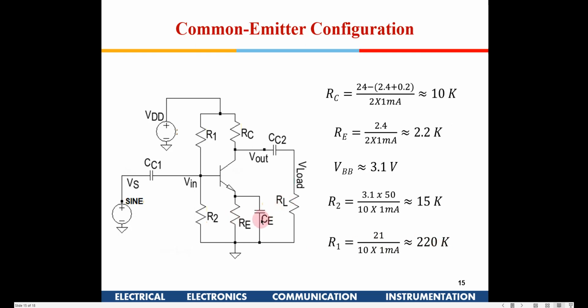So now these capacitances, generally their values depend on your frequency of operation. R and C together will act like a high pass filter, right? So depending on your frequency of application, for whatever your desired frequency, they should bypass RC. Similarly this is also a high pass filter where high frequency will be coupled here. So the values of these capacitances depend on your frequency of operation, right?